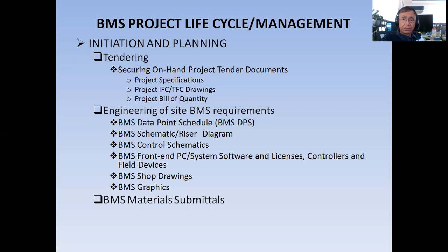Then you have to sit down with this consultant and explain your BMS material submittals, especially the first four points: BMS data point schedule, BMS schematic riser diagram, BMS control schematic, and BMS front-end PC system software and licenses, controllers, and field devices selection.